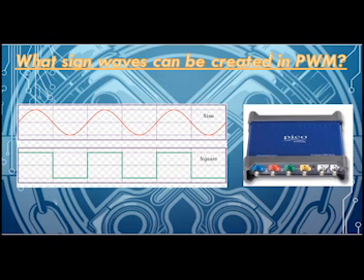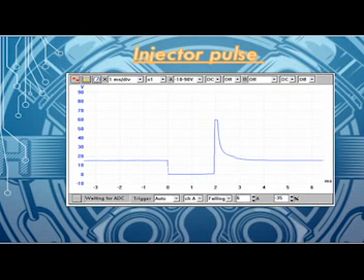Just right here, I've got another diagram of a square wave and a sine wave. The main difference between each of them is how they look across a picoscope reading. As I said before, with the square wave, it is quite often that the sensor being registered through the picoscope would have an IC chip, whereas with a sine wave, there's a good chance that you're not going to have an IC chip in that sensor.